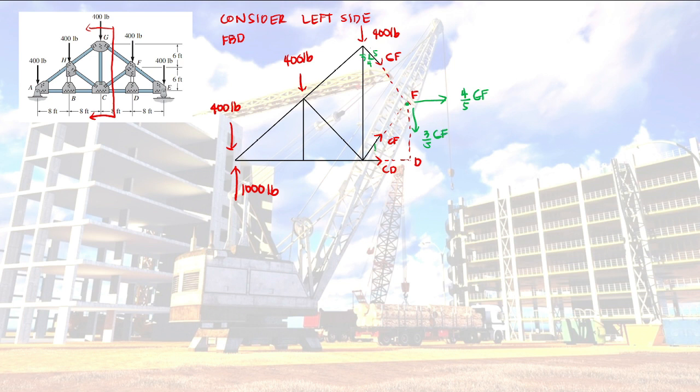Also here, yung CF natin, our slope triangle here is also 3, 4, 5. So, saan natin nilalagay yung component niya? Nasa end joint din. So, therefore, it is also here. So, we have yung vertical component, 3/5 CF, and we have the horizontal component na 4/5 CF. Okay, so after our component, we can already use our 3 equations of equilibrium.